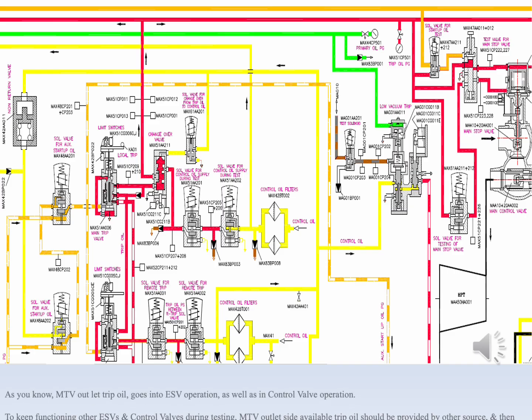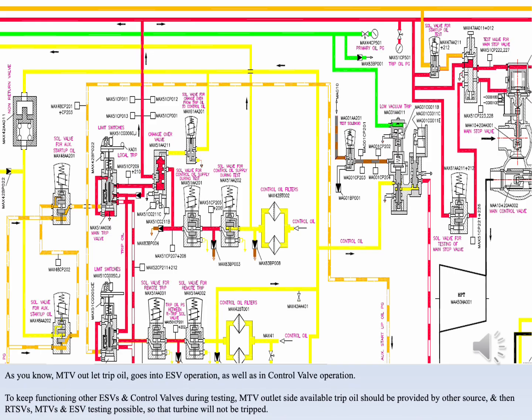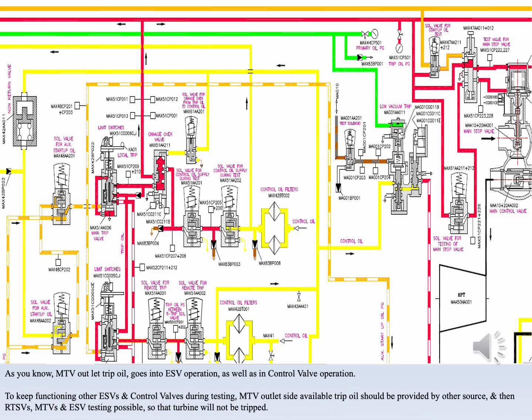As you know, MTV outlet trip oil goes into ESV operation, as well as into control valve operation. To keep other ESVs and control valves functioning during testing, the trip oil available at the MTV outlet side should be provided by another source, and then RTSVs, MTVs and ESV testing is possible, so that the turbine will not be tripped.